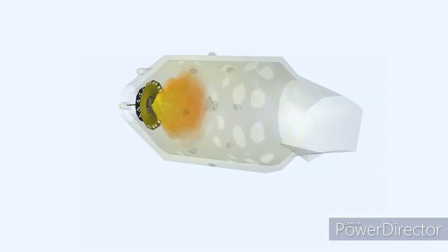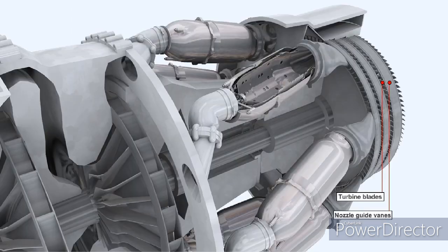The turbojet is a heat engine. The higher the temperature attained in combustion, the greater the expansion of the gases, and hence the greater efficiency of the engine. There is, however, a limit to the amount of heat that can be released into the turbine from combustion. This limit is imposed by the materials from which we manufacture the nozzle guide vanes and the turbine blades.